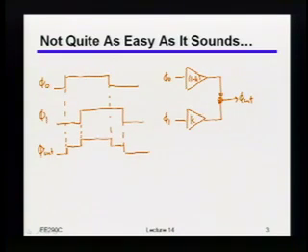In fact, there's another thing which is related to, remember we said something about signal slopes and sensitivity to errors and things like that? What's the slope of the waveform here right when you care about it? It's 0, right? It's completely flat. So you can put a tiny little bit of noise and completely make the timing undefined. You have no freaking idea what the edge actually is doing. Okay, so clearly this is bad. So now, what do you have to do to fix this?